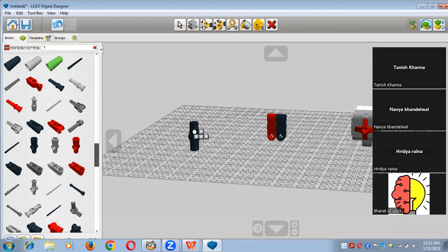So just click on that, and after that drag your mouse in any direction, and you receive the same copy of that object. No need to find it again and again during designing, because it's a completely time-taking process. But with the help of this tool, we can reduce that. Okay, we can save the time. So this is the role of the clone tool. And the hinge tool.